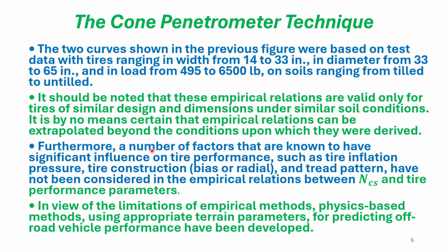Furthermore, a number of factors that are known to have significant influence on tire performance, such as tire inflation pressure, tire construction, bias or radial, and tread pattern, have not been considered in the empirical relations between N_CS and tire performance parameters.